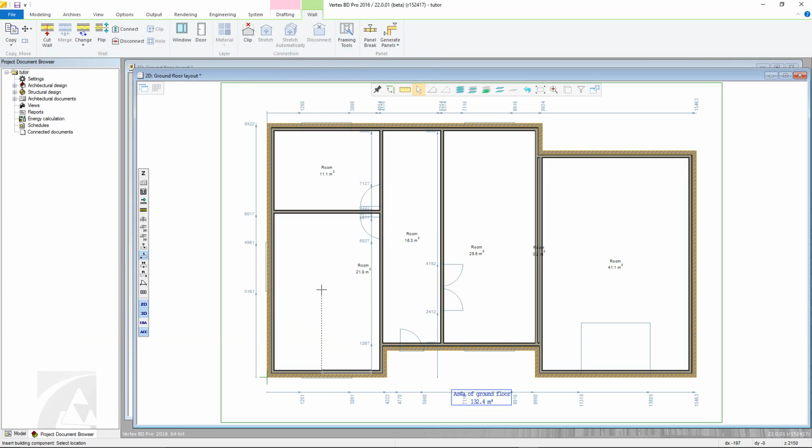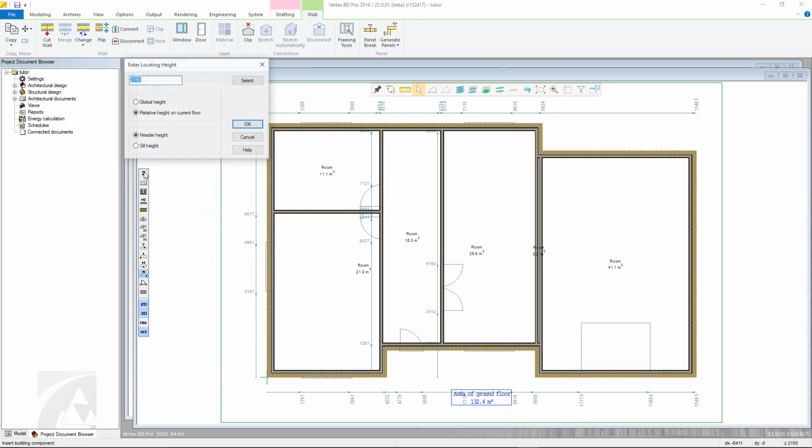By default, the cursor is attached to the left side of the window as viewed from the exterior side of the wall. But you can change the reference point in the contextual toolbar with the left, middle, and right buttons. The window header height can also be adjusted from what was previously set up in the 3D levels. This will be on a window-by-window basis. However, BD will keep these adjusted settings if adding in multiple instances of the same window.